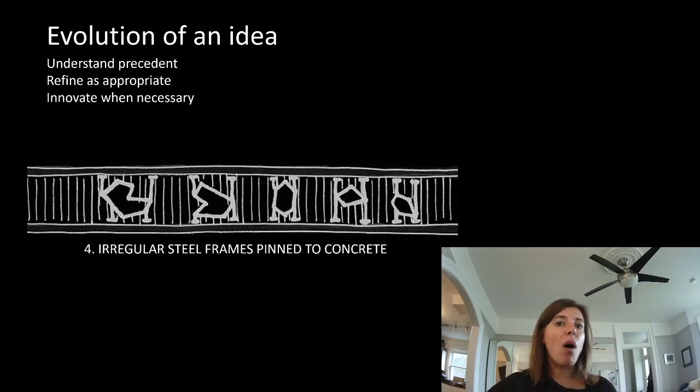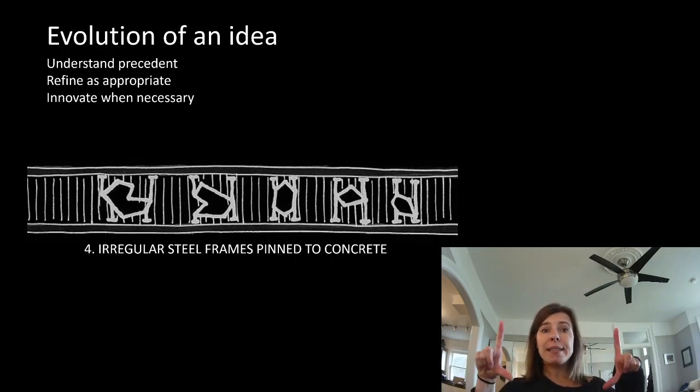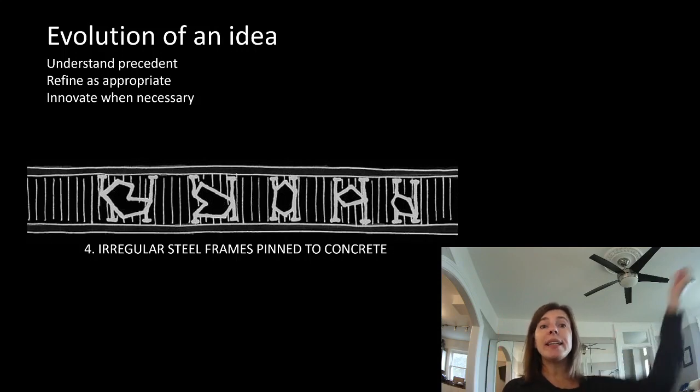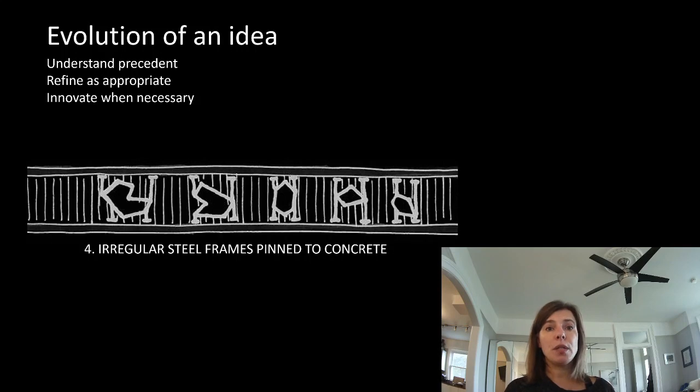We would resolve all of those 3 degrees of freedom. I mean, we know it's actually 6 degrees of freedom, but we would be able to prove that we had equilibrium in the y direction, the x direction, and spinning about z. That we could do 4 pinned connections now instead. So a lot easier to detail, a lot easier to install, especially quickly on site.